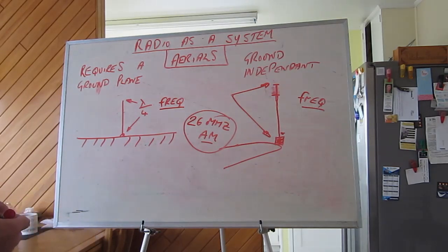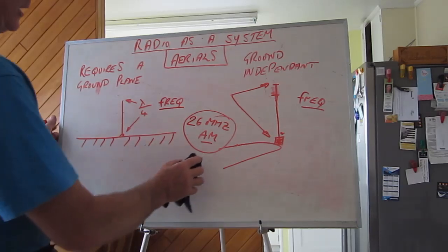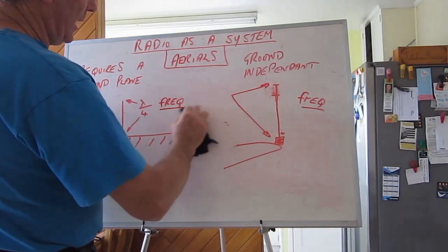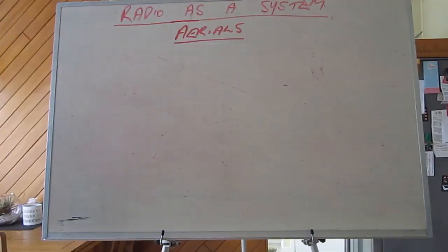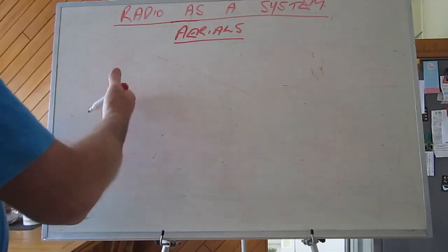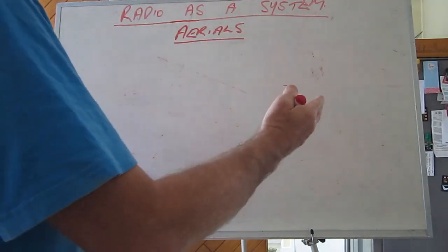Most other antennas that you come across require the antenna to actually be trimmed, and they will come with a trimming chart or some form of instruction. Okay, the other issue with respect to aerials and poor installations of these aerials is a lack of understanding about how an aerial is adversely affected by adjacent structure. And this issue affects all aerials, whether they require a ground plane or whether they're ground plane independent.